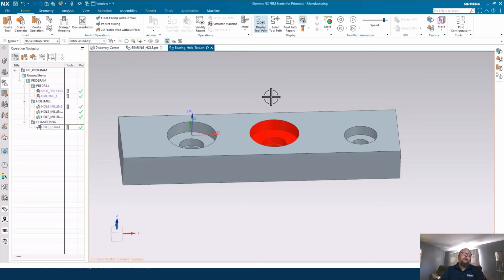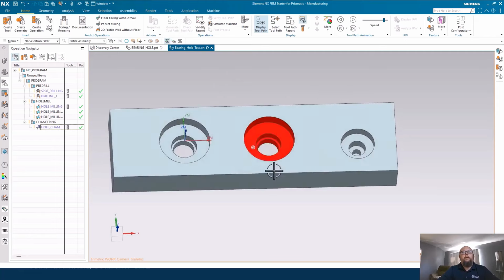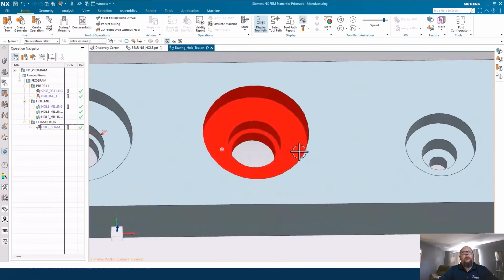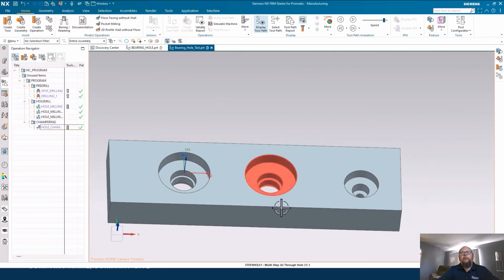and within a certain tolerance, we're going to do some different processes. For my scenario here, this kind of fictitious scenario, we have our bearing hole process, which is going to be for a default bearing hole feature for us. However, if the feature is red, instead of milling this diameter 3 to size, I want to mill it undersize and then ream it to finish size.